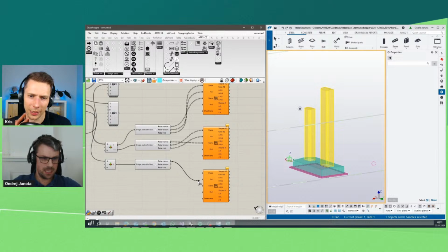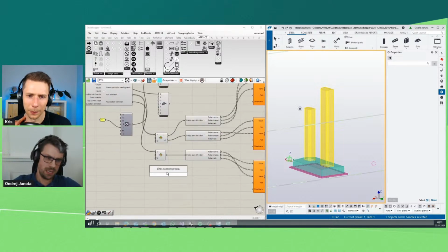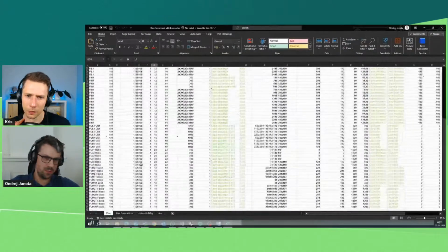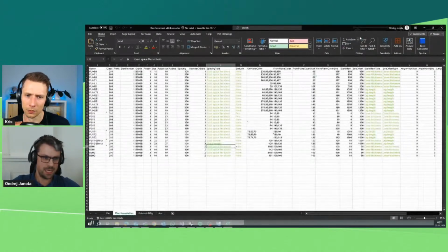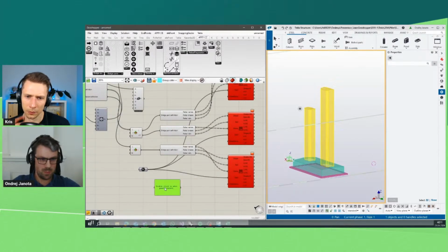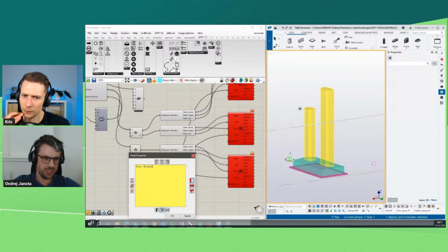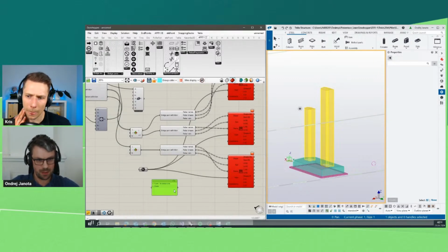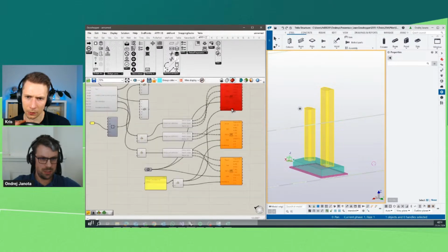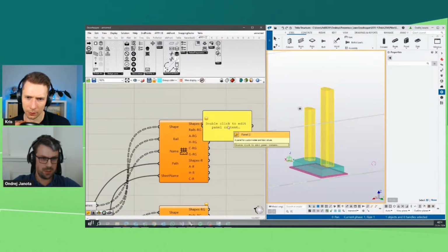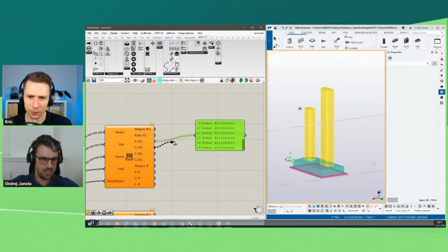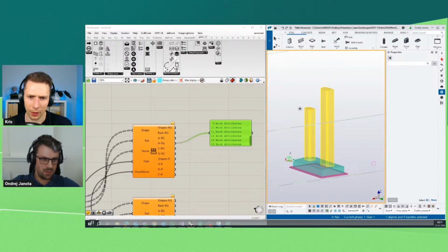As you can see, it's the same component that you presented before. This is the keystone, and you only alter the way the input is created. We have Excel, it's already prepared, so we link our component to the Excel. We define in which sheet is what bridge or pier part, and then we produce all the data. Here you can see what our component produces. Here we have shapes, rails, and attributes, and we are almost done.